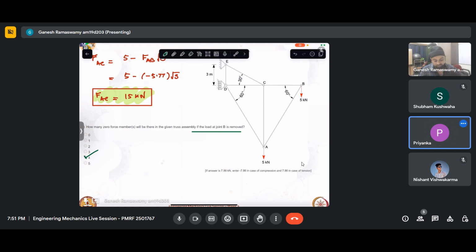No, see, including equilibrium would be total number of equations. So if by equilibrium we have three equations, let us say, at our disposal. For example, for this joint, we have three unknown forces here, which get revealed when we cut that joint. So the equilibrium equations that we have for this joint is two. So how many additional will be required to uniquely solve? From that you can figure out, right? The total number of equations required is three because there are three unknowns. Equilibrium provides only two. So additional implies what is required over and above the equilibrium.